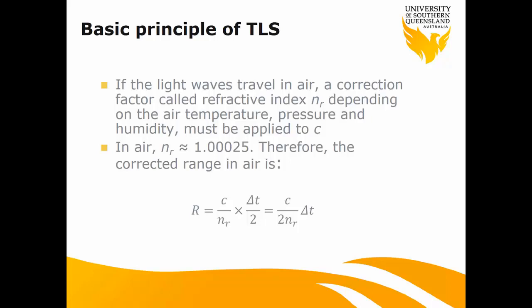That means in the air, the laser beam always travels at a slightly slower speed compared to the vacuum. So if we consider the refractive index, the range value can be calculated by this formula, if you can get the time the laser beam travels.